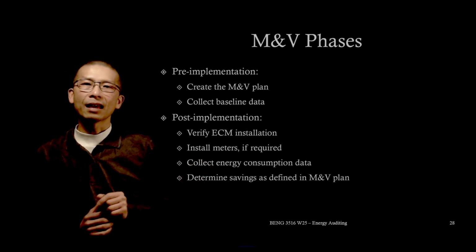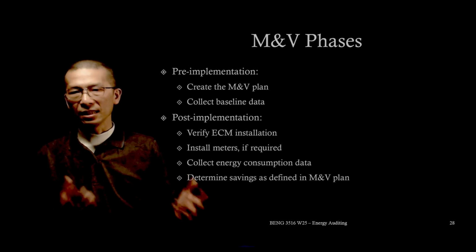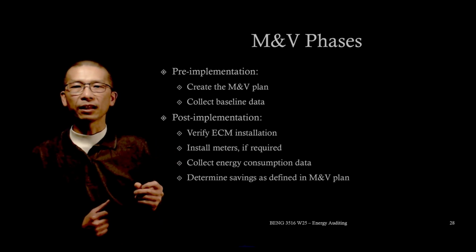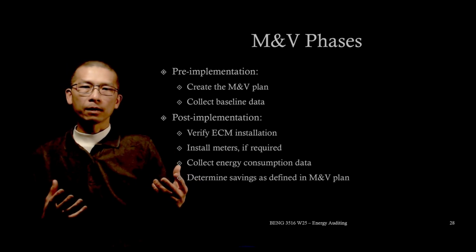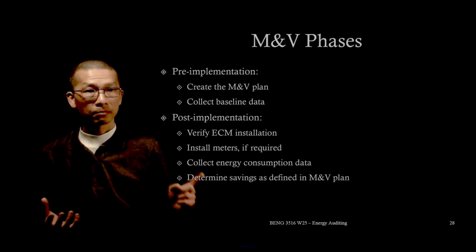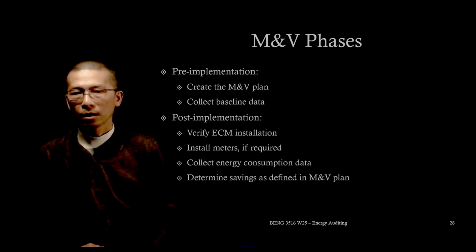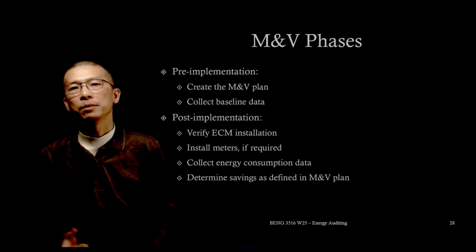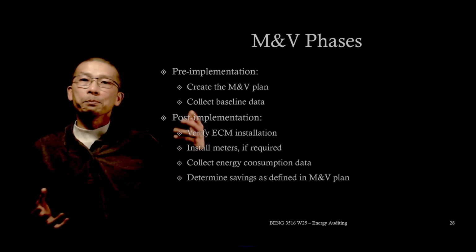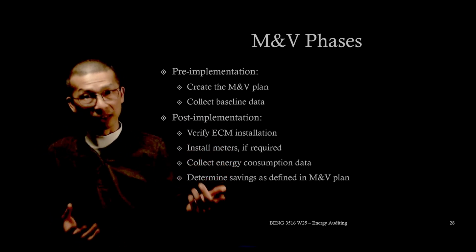Collect energy consumption data during the reporting period when the ECM is operational. Record the energy consumption data using the same methodology as the baseline to maintain consistency. And determine savings, that's the last step. Compare the post-implementation energy consumption data with the baseline, adjusting for external factors, of course, if necessary.